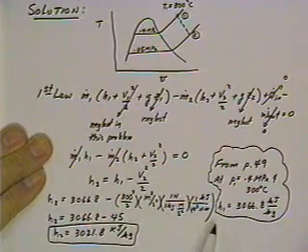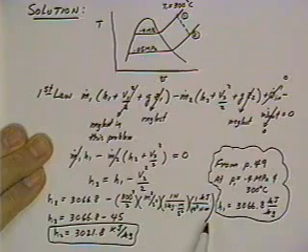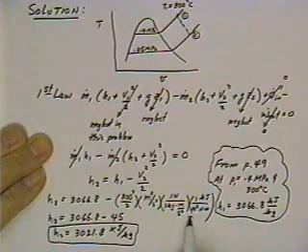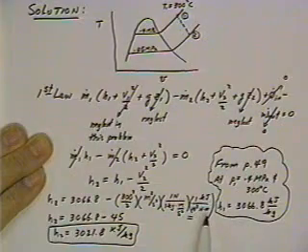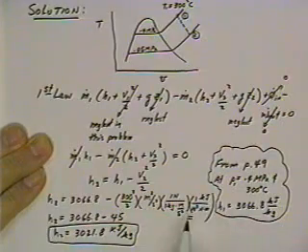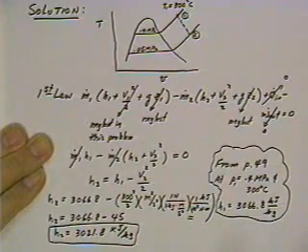So when you plug in all those units, cancel them out, making sure your units are compatible. This is real important to remember, you've got your answer in kilojoules, so it's real important to remember this 10 to the third Newton meter per kilojoule conversion. Otherwise you get huge answers that are in error by a factor of 1,000.